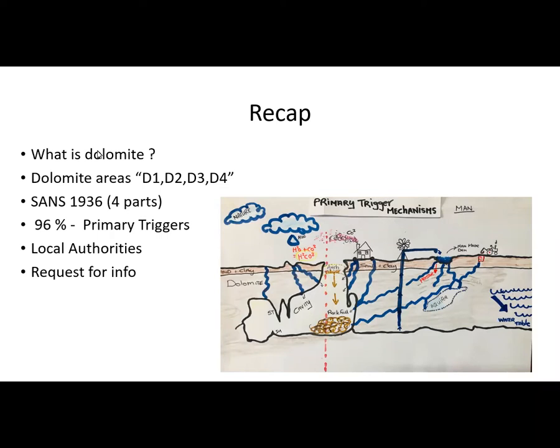The little picture I put up in my last session shows a lot of blue lines, which are fissures, cracks and joints. That's natural, and they act as passageways for water to ingress into the soil and get down to the water tables. Over time, that dolomite does dissolve, and it triggers things such as dolines and sinkholes.